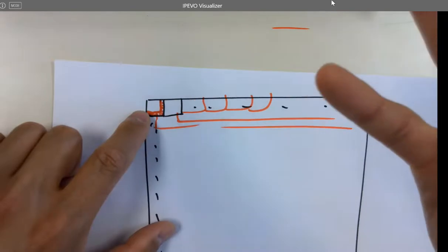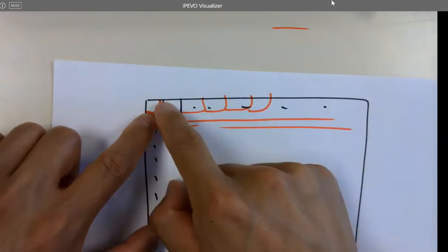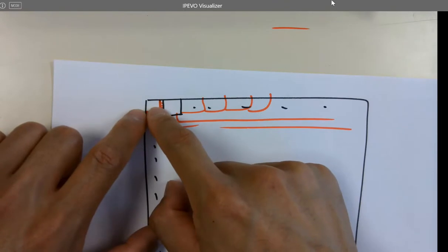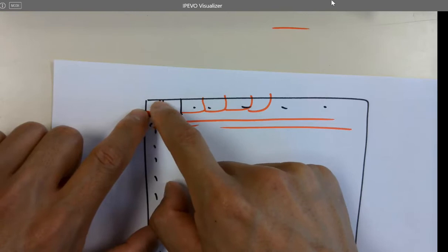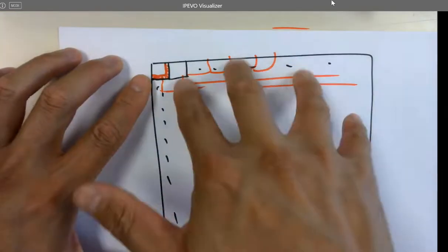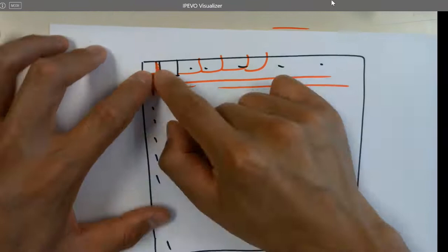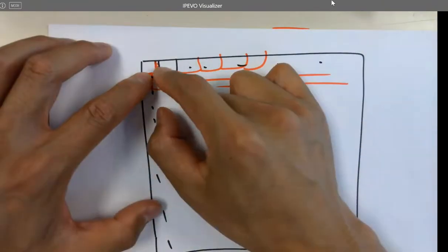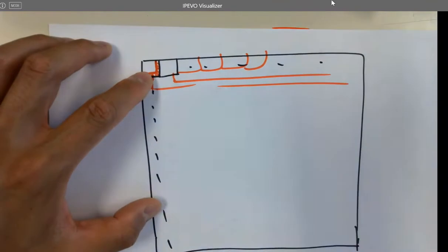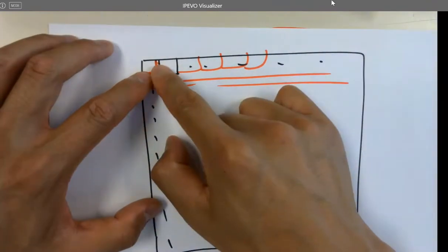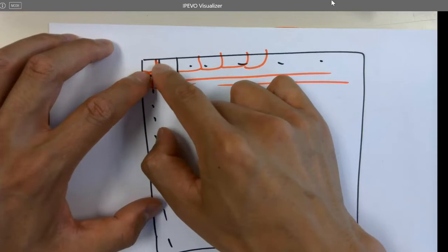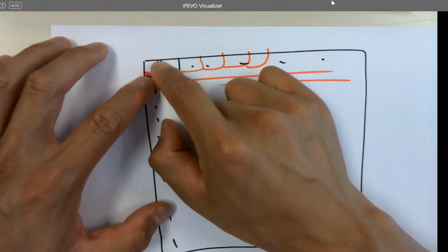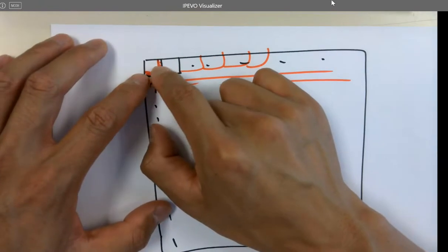It's gonna be faster. So if each one has 1, you can convert that photocurrent into voltage immediately. But a lot of times you don't need that because it takes time to process all the pixels. So even though you have voltage there ready to be taken out, it's gonna wait there for a while, probably just microseconds or something. You don't need that to be that fast. And also it's a huge weakness that the aspect ratio is too small. That's why you don't want every single pixel to have an OpAmp.